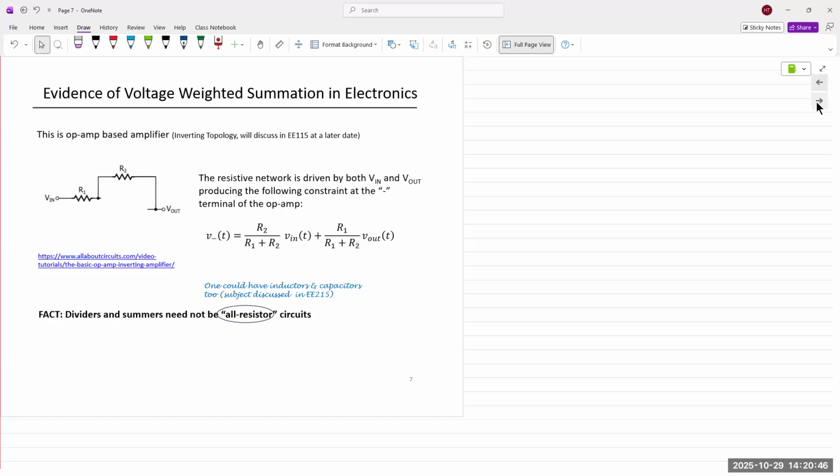Okay. So an op-amp or an operational amplifier is denoted by a large triangle like this. It has an output. V out is taken there. This is the inverting and this is the non-inverting terminal. At the inverting terminal, we have an input resistor. We call it Ri.